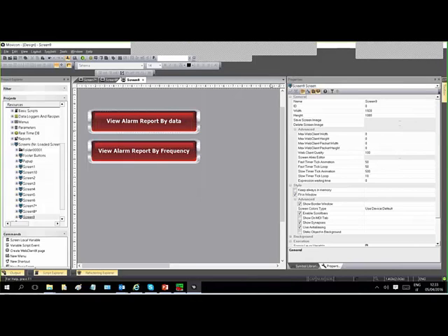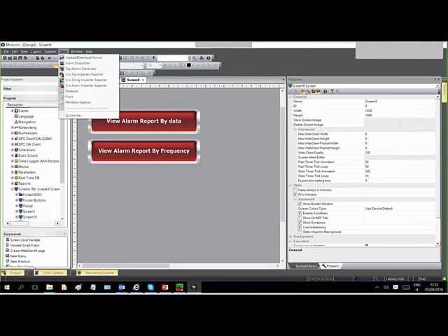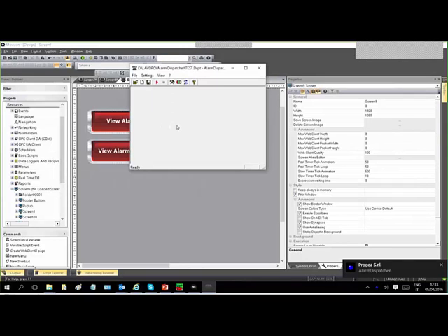Again, about the alarm, we could configure the alarm dispatcher to dispatch these messages. So, for example, I go quickly to tools, alarm dispatcher. This is the external tool that Movicon uses to dispatch the alarm. What you have to do externally to the project is just configure a plugin that is common on your PC, that is the plugin used by the system to send these messages for the alarms.